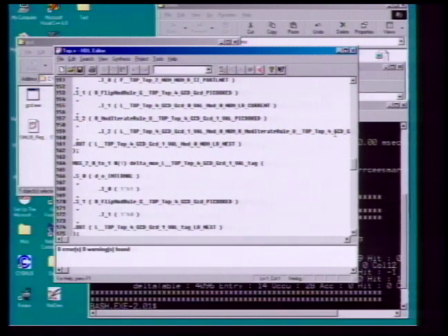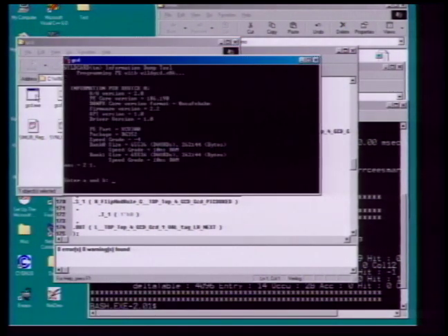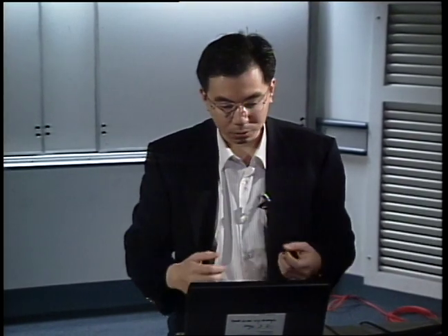But I can take this Verilog file, send it through Foundation tools, and create a configuration for the FPGA in about 10 minutes. And I did that before I got here. So I have just put in the FPGA, and now I can run a program to download the configuration that was created for the application we just developed onto the FPGA, and now we can send numbers to the hardware and compute the greatest common divisor between two integers in hardware.